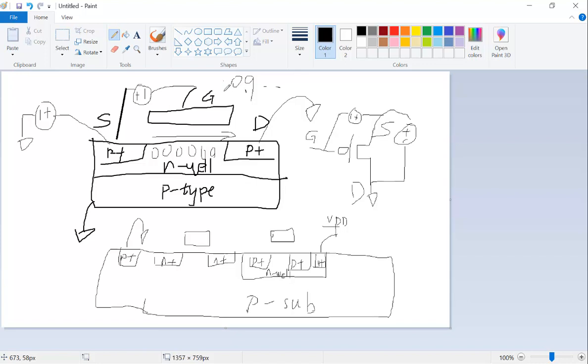So they're not getting shorted. And then drill a hole to the top. We use the vias, right, the via, and then have another layer of metal, and then drill holes on the top, another layer of metal. Just keep going to the top, and then eventually you've got a chip. You can look from the top to look at the chip.